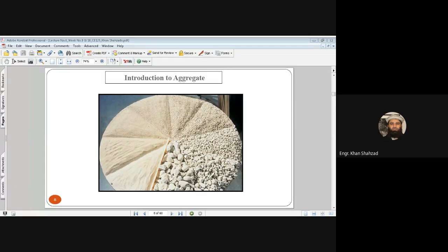Okay, so this is actually the gradation of the aggregates, or the well-graded material which has all size particles. When you have such type of materials, then there will be fewer voids in the concrete and fewer voids in the aggregates. So for that you will need less cement paste and a lesser quantity of water as well. So this is just given for your information and knowledge, as a sample of material which shows well graded aggregates. Is it okay?